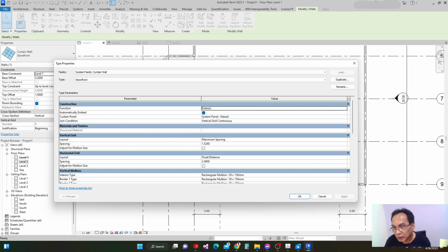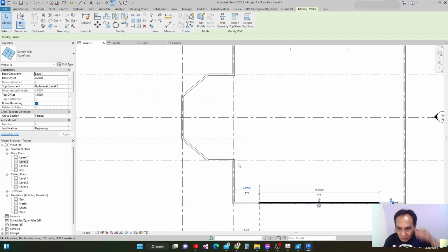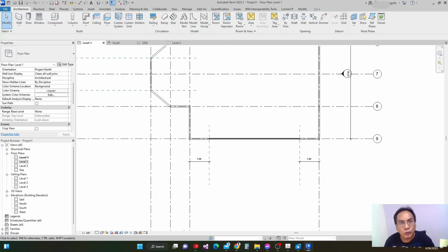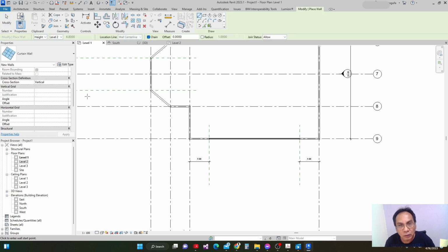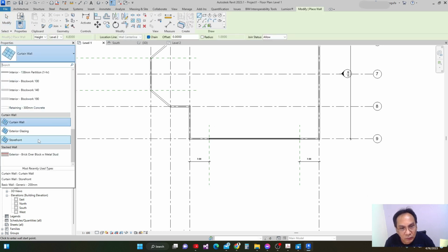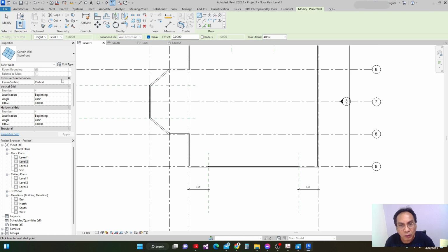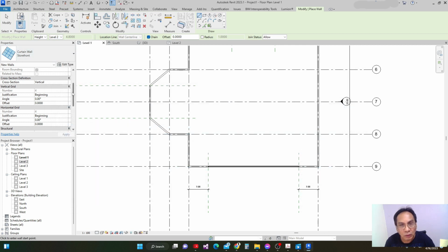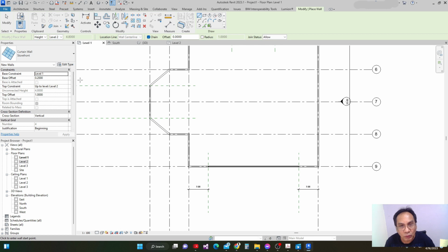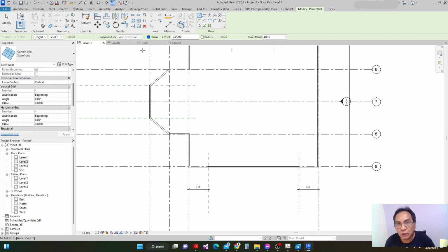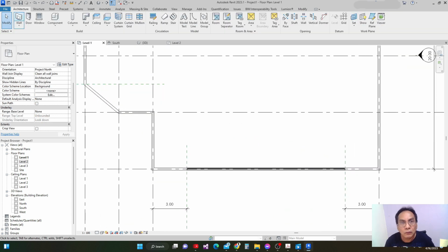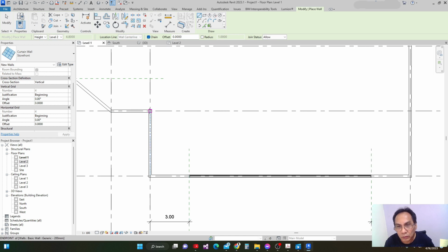Let's have this checked, and then okay. Let's create another wall, and we'll select this storefront, and again go to automatic embed. Okay, and then what I'm going to do is the same. We have 0.1 and 1 also, and check the chain, and then wall storefront.